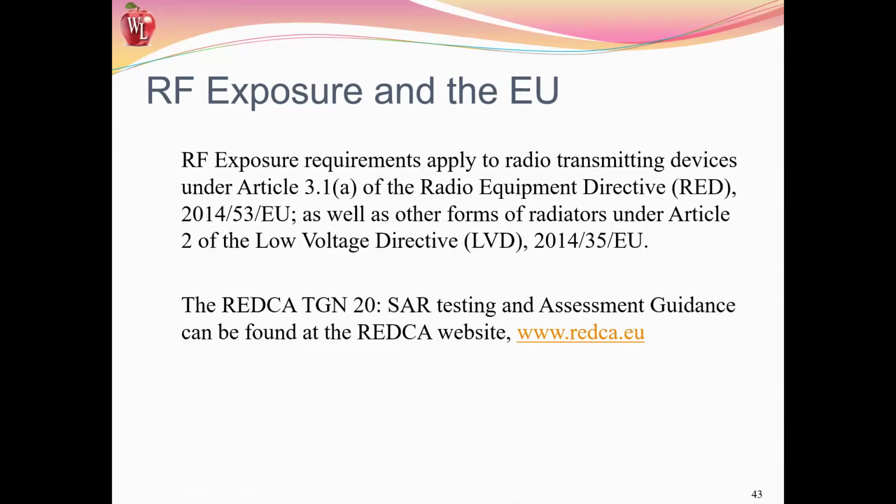They do have RF exposure requirements in Europe as well. Of course, that falls under Article 3.1a of the Radio Equipment Directive, which is a safety requirement. The device has to be safe, and it's not just electrical safety, it's also for the RF hazard.